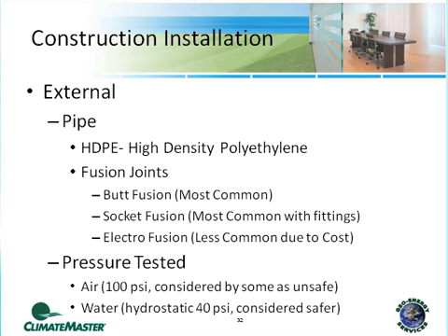As far as pressure testing, most of the time if you're doing an air pressure test, most people run it to about 100 psi. That's not very safe, quite honestly, because compressed air at 100 psi has a tremendous amount of energy built into it. So if there were to be a leak and a guy happened to be real close by, that could be pretty nasty.